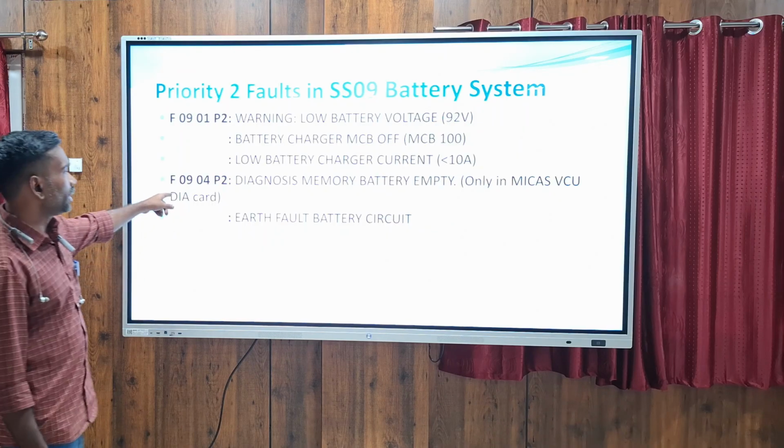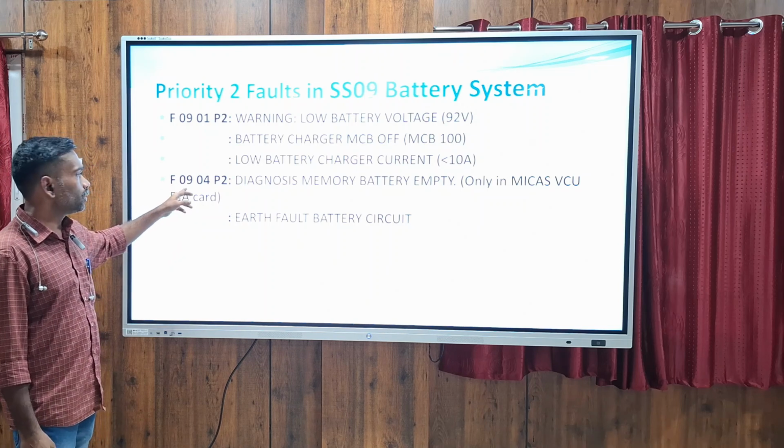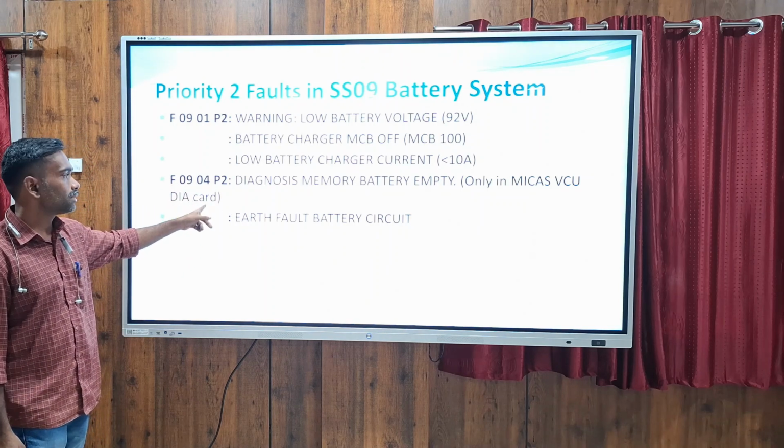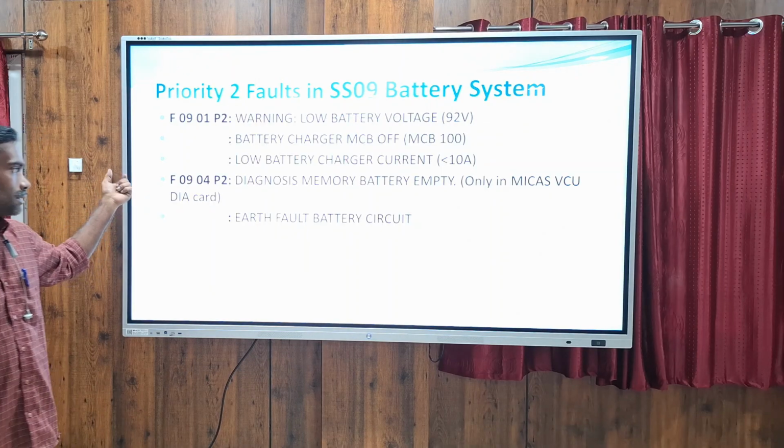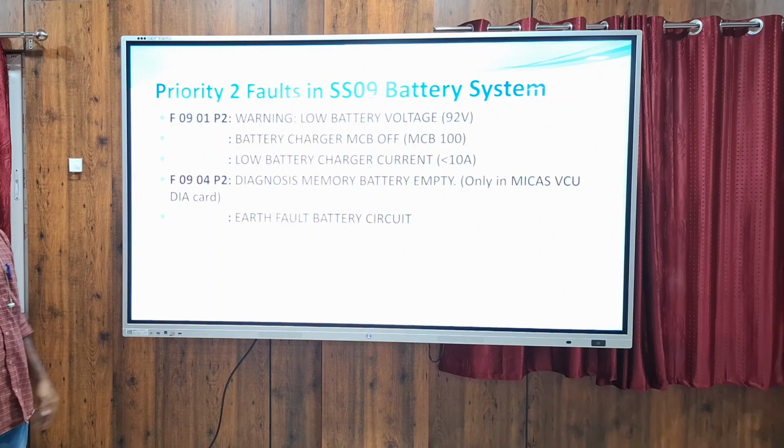This fault is for Mika lock only. In Mika CCU, earlier one DA card is there. There one RTC battery will be there. If that battery voltage is drained, this fault will come. Now it is not there.